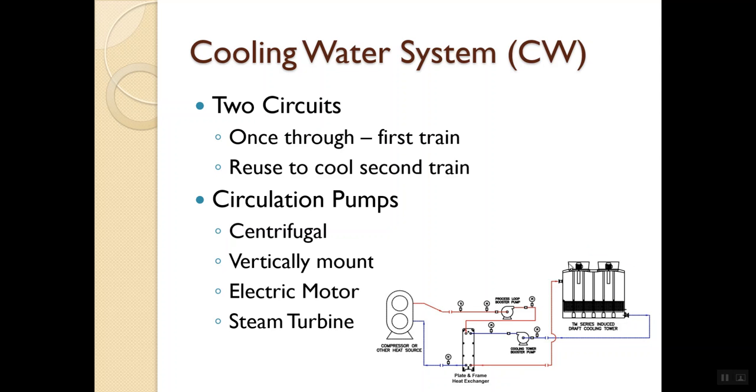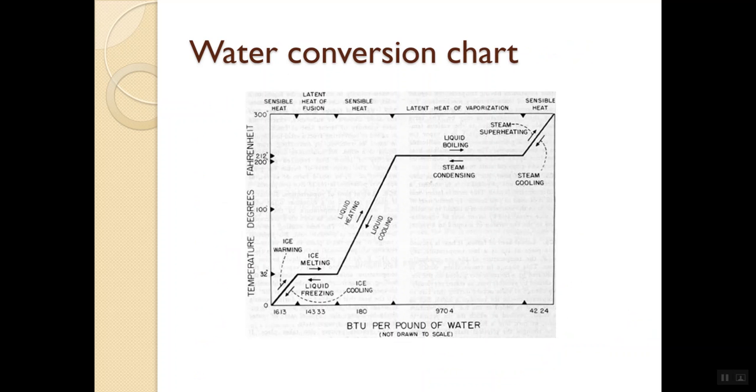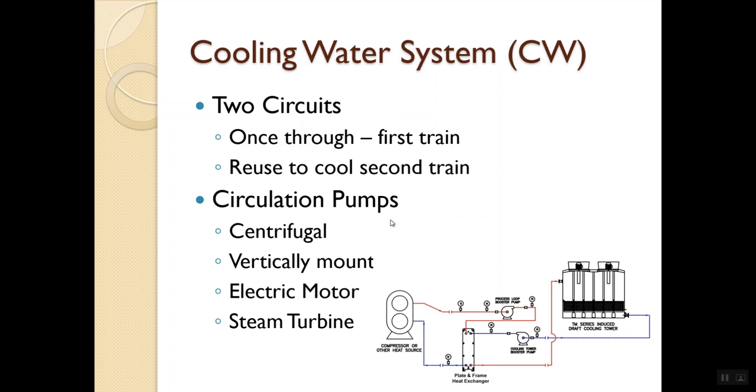When we run a fan like this, we evaporate water, and that evaporation is what we consider an endothermic process, which allows the temperature of that water to cool down. The heat it takes to boil water, if we don't add heat to it and that water evaporates, if we don't have a stovetop or a natural gas fire, then it pulls heat out of the remaining water. We talked about this a bunch in equipment class, and we'll talk about it in the lab a little bit more as well. But that's what we're doing there.